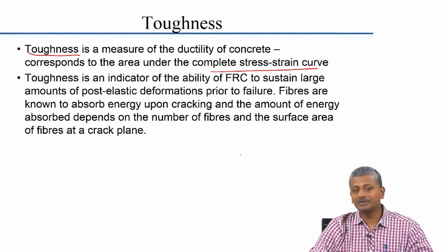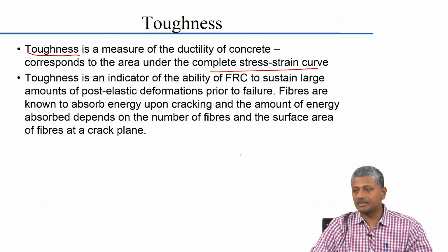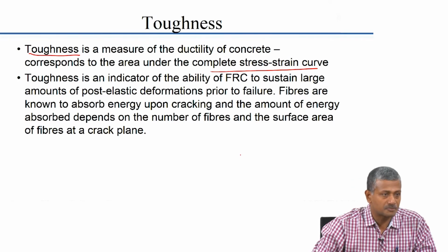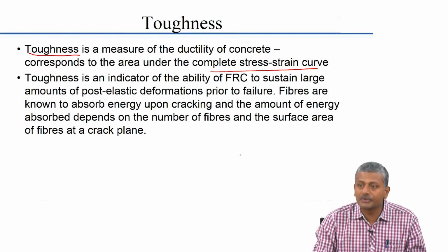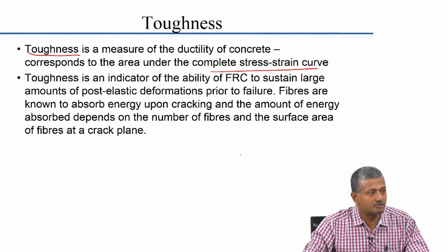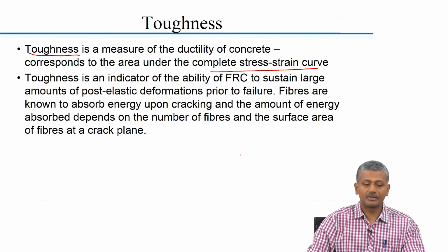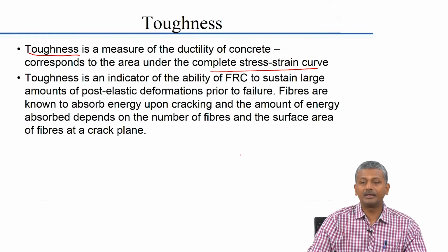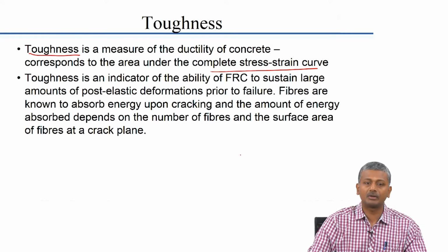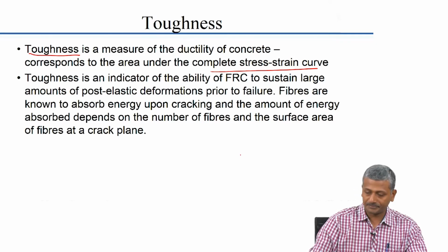It is more the toughness of the concrete, okay, toughness. And toughness especially is used as an indicator with respect to fiber reinforced concrete, because it is able to sustain very large deformations before failure. And so, again, fibers, as I said before, absorb energy upon cracking, and the amount of energy absorbed obviously would depend on the amount of fibers that are actually available in the system and the aspect ratio of the fibers, because that will define the surface area of the fibers that are available at the crack plane.